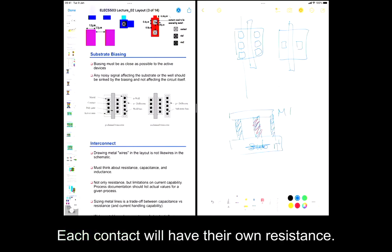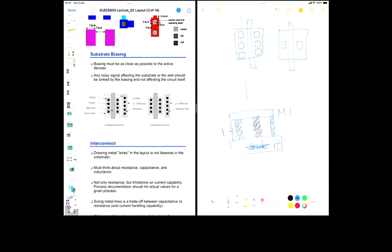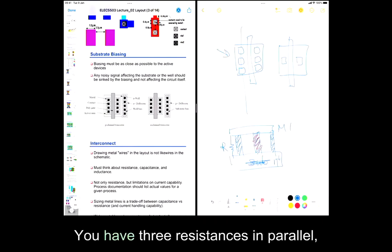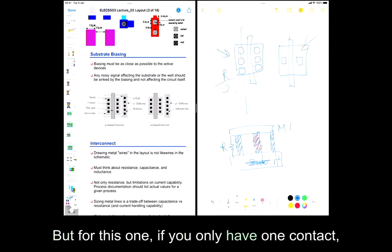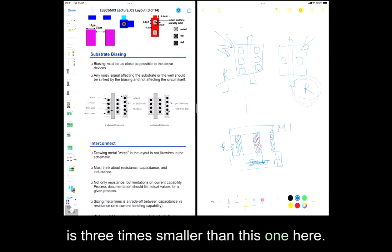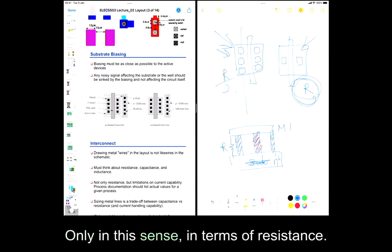Each contact will have its own resistance. It will be small, but still a fair amount of resistance. So what kind of resistance do you have? You have 3 resistances in parallel, so it'll be R divided by 3. But if you only have 1 contact, then it'll be R. So the resistance for this one is 3 times smaller than this one here. Therefore, the more the better in this sense, only in terms of resistance.